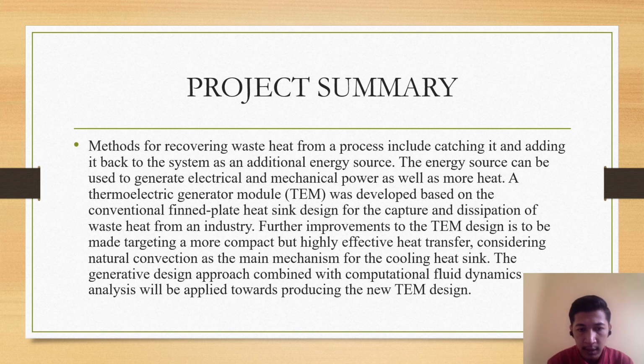developed based on the conventional thin plate heat sink design for the capture and dissipation of waste heat from an industry. Further improvement to the TEM design is to be made, targeting a more compact but highly effective heat transfer, considering natural convection as the main mechanism for the cooling heat sink. The generative design approach combined with computational fluid dynamic analysis will be applied toward producing the new TEM design.